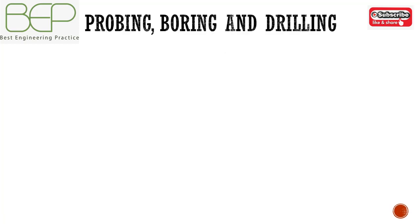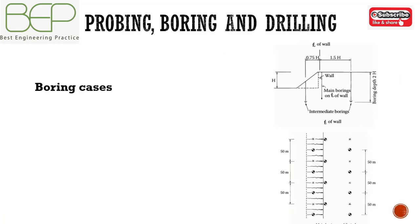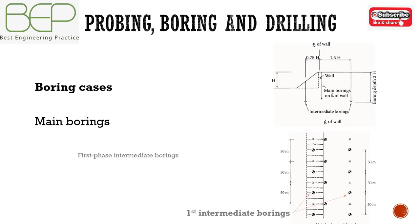Three groups of borehole may be used. The main borings at 50 meter centers along the center line of the wall are taken to twice the proposed wall height below the upper level, or to a known geological stratum. The first phase intermediate borings are carried out after the completion of the main borings on the active and passive side, again at 50 meter centers along the proposed wall position.